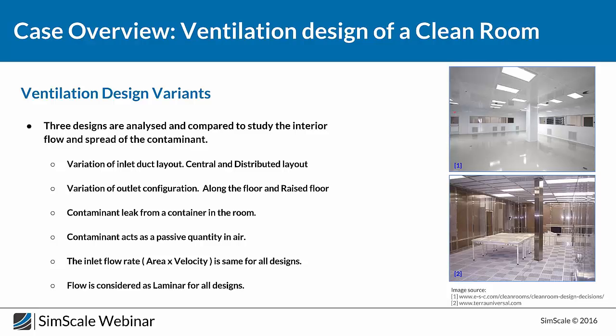We have kept the inlet mass flow rate constant for all of the designs to give them a fair comparison in the end when we are looking at the results. For the case of these designs, we consider a laminar flow condition, which is completely realistic, but there are also turbulent variations where the inlet is intentionally turbulent. But as I said, in this webinar, we focus on laminar cases.